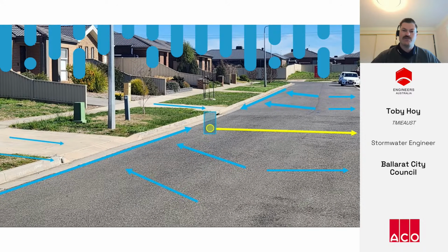The road sheets both ways, left and right, towards the curbs. This road is at 2.5% grade. There's a legal point of discharge at the bottom left corner of the picture, flowing out into the curb. We also have driveways sheeting water into the curbs. In extreme events, the grass nature strips will also sheet some water into the curbs.